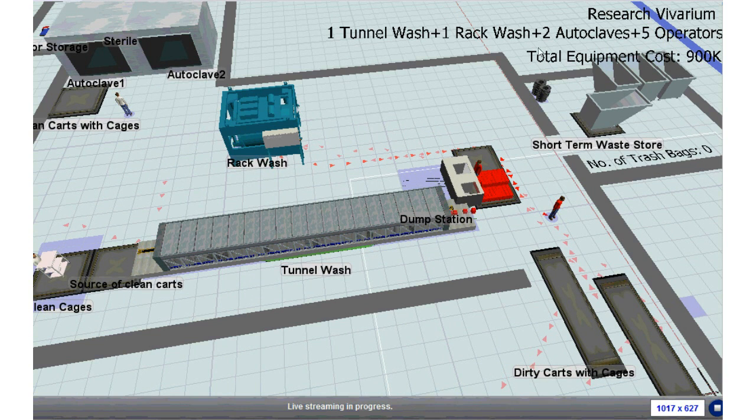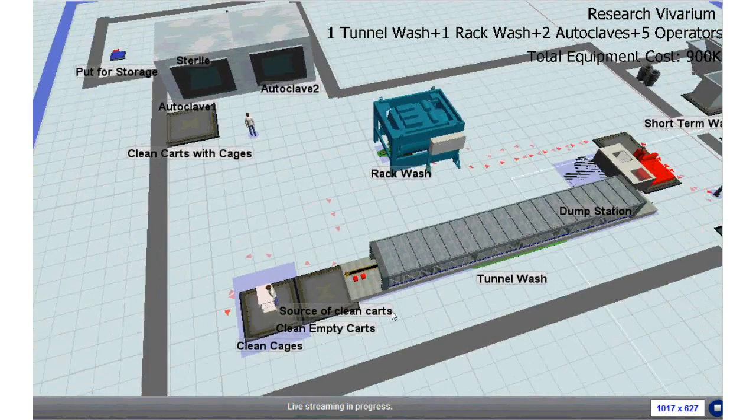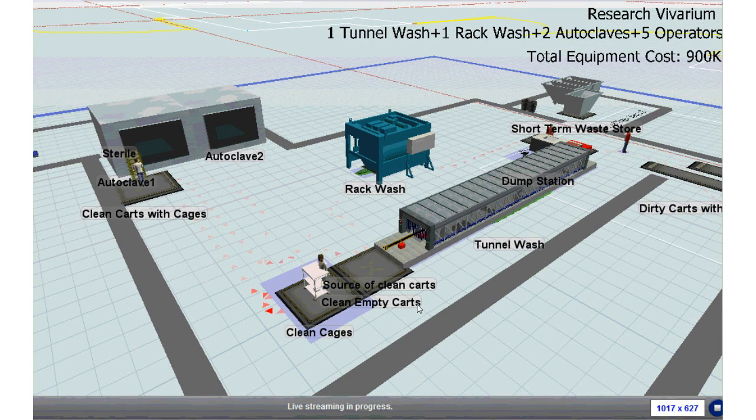I just want to say something else about the process flow diagram. If there's an existing facility or even a new one that you're planning, a key validation step is to always produce a process flow diagram. We make sure that we've completely understood all the inputs and outputs, the speeds of each of the operations or their current throughputs.